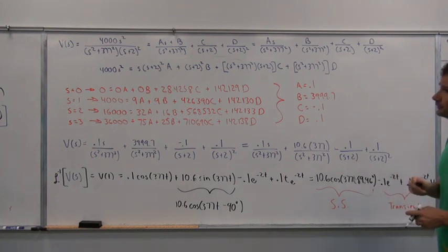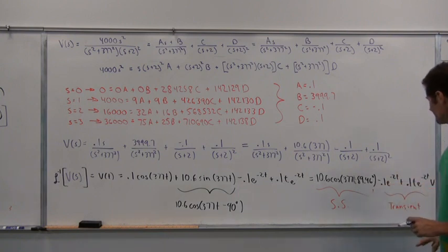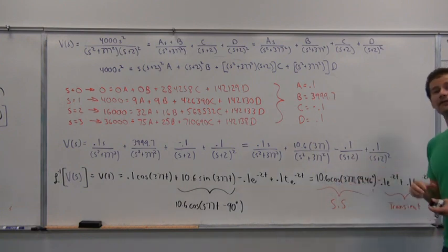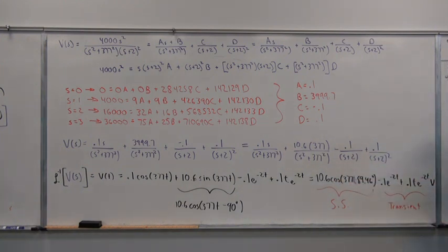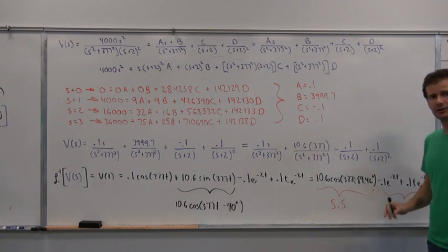So let's go through sinusoidal steady state analysis with phasors, not worry about the transient, and see if we get the same steady state solution. If you look at the book, I plotted this, and you don't really see much of that transient. This is a good example of why we may not care about it. It's a very, very small transient period that we introduce into the voltage across that capacitor, and we may only care about the steady state solution.